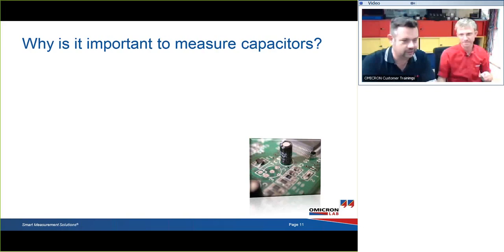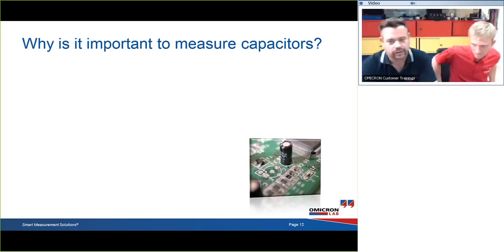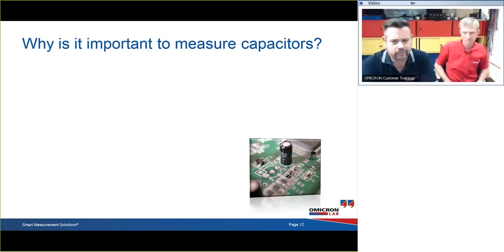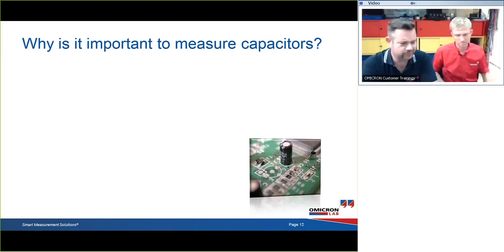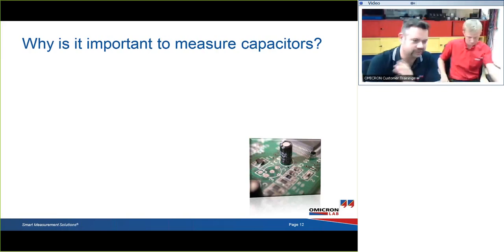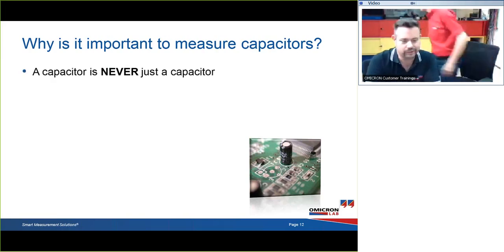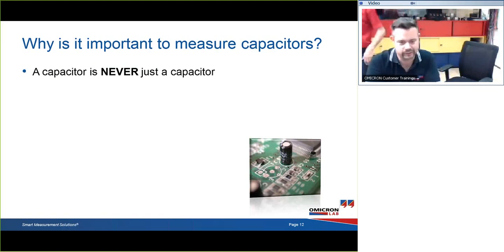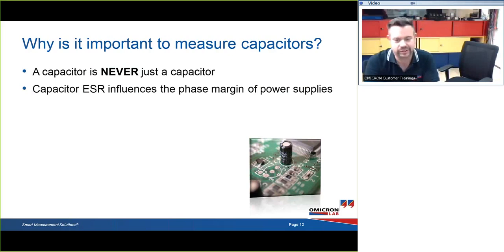Well, thanks a lot, Florian. So, why is it important to measure capacitors? Everything is in the data sheet, we think. No, it's not. First of all, the reason why we need to measure capacitors is because a capacitor is never just a capacitor. Further on, capacitor ESR influences a lot of things when we are developing power supplies.